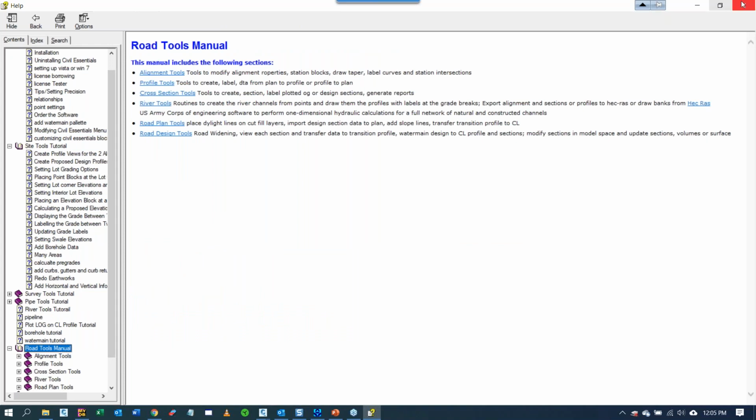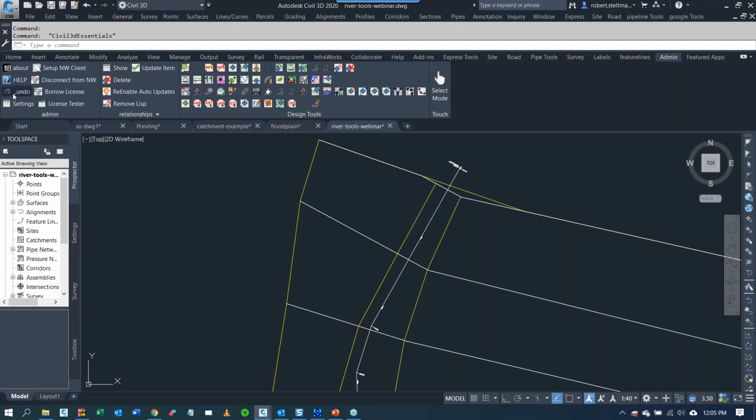Okay, and all of our routines begin with an undo mark, so it may undo a number of AutoCAD commands. Some of our routines do use the command as if you were typing it from here, and we fill in the blanks. So this one will go to the beginning of our routine as opposed to the Civil 3D, which goes back one command.